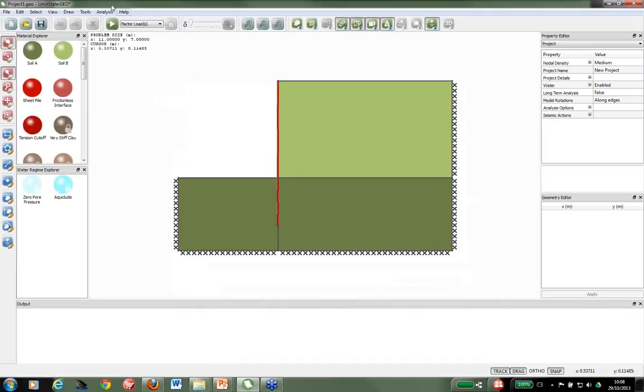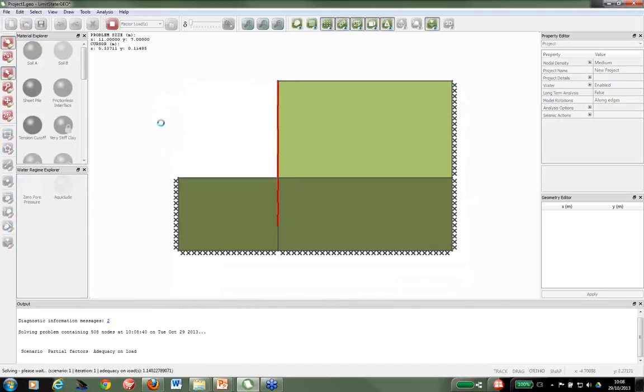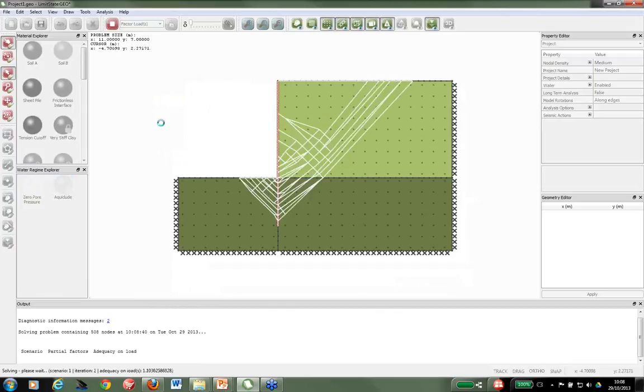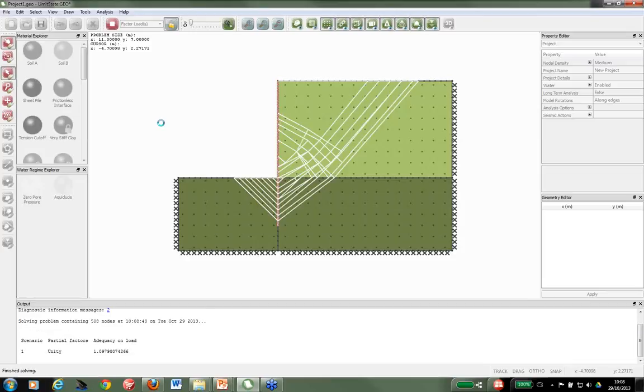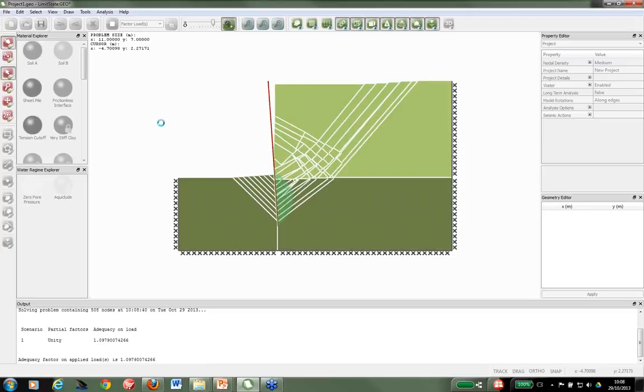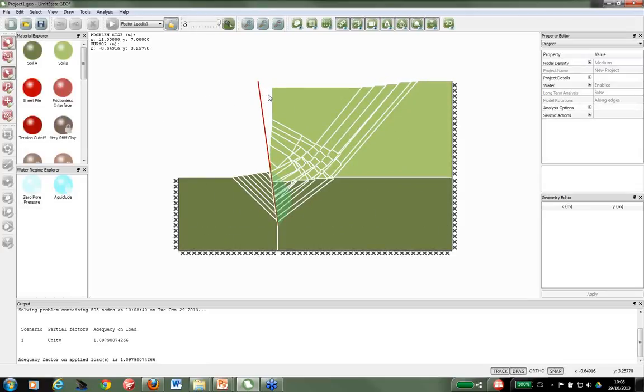So here we have a sheet pile wall in cohesive soil. If I click solve on that, it finds the collapse mechanism for me. And because it's an undrained soil, I get a tension crack opening up by the wall, and here it's able to display axial force, shear force, and particularly the bending moment in the wall due to the applied stresses. And those can be exported to a CSV file for further analysis.